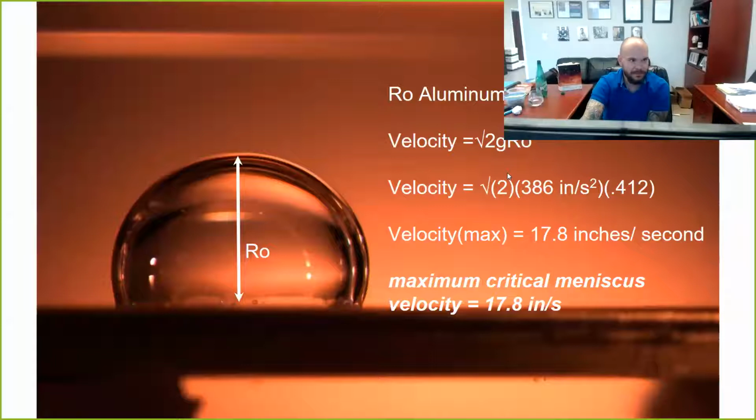All right, so we know the speed that we need to maintain once we enter the casting cavity. Now we've got a serious issue, because if you notice, that drop height is only 412 thousandths of an inch, which means if we're dropping metal more than half an inch, we've already screwed it up. For most castings, let's say a 3 feet tall or 1 meter tall casting, by the time you're in the runner, that metal's traveling about 200 inches a second. So we've got to go from 200 inches a second through the gates into the casting cavity at less than 18 inches a second. That's a tall order. That's a tricky thing. We'll talk about that in a second, but let's go back to that terrible conical pouring cup.